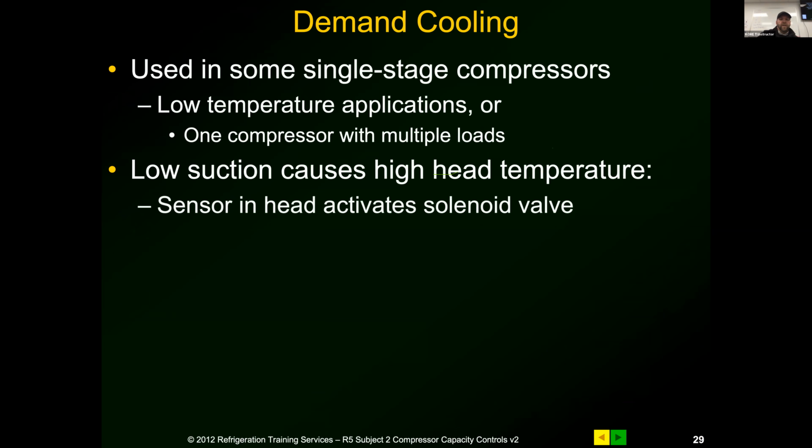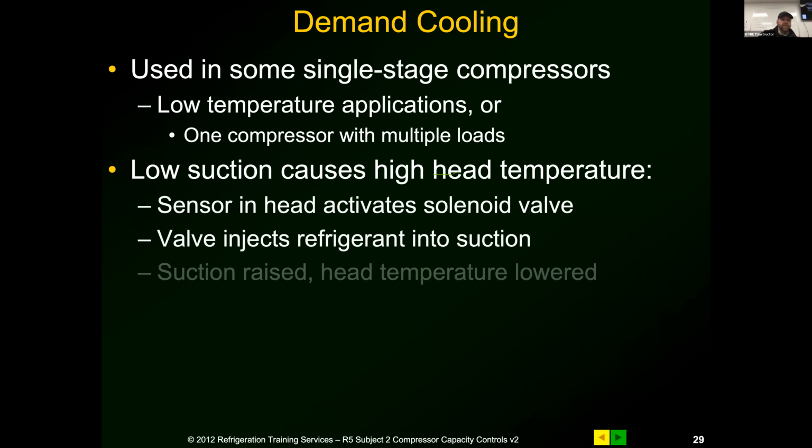So low suction causes high head temperatures. Sensor and head activate solenoid valve. Valve injects refrigerant into suction. So suction's raised, head temperature is lowered.